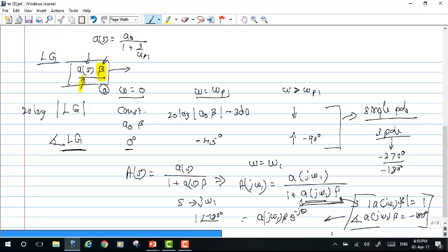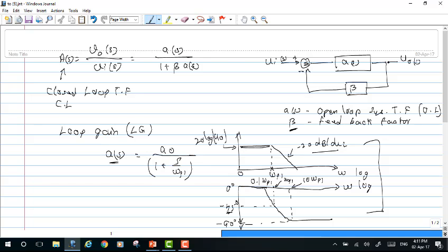So when this entire term goes to negative 1, what happens to the closed loop gain expression in that case? It tends to become infinity. Under this condition, the circuit starts to amplify its own noise and starts to oscillate at a particular frequency, and the entire closed loop system is said to have an unstable condition.